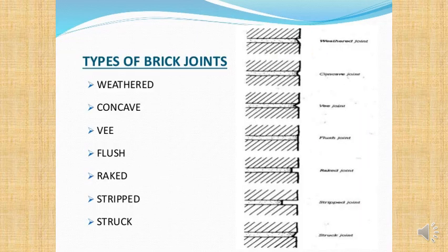So when you stick the bricks together, this is just a very basic example, but there's a few different joins. One is where you have a flush join. That's the one in the middle there. That's basically where you're making the mortar flush with the face of the brick or the block. A V is where you cut it into a small V section. Concave is where you sort of run a teaspoon, and so you have a circular hollowed out section.